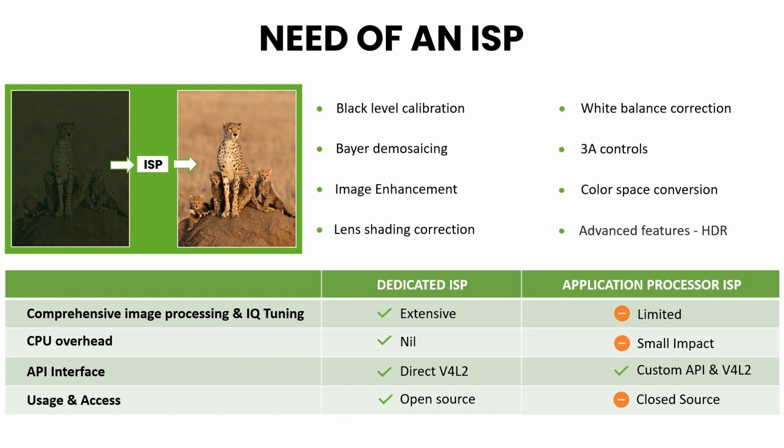However, in the case of the ISP present in the processor, custom APIs could be required to access the camera output data. For example, the NVIDIA ISPs use an API called libArgus through which the user can grab frames from the camera. Although libArgus is new, adoption of libArgus based cameras has been growing with support from NVIDIA.